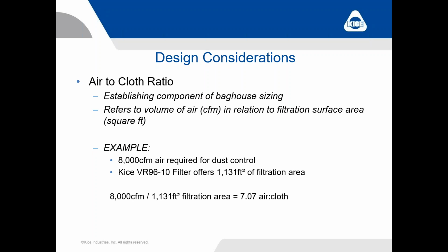If I take a filter bag out of this baghouse, cut a slit down one side and lay it flat on the ground, I can measure the flat surface of that bag. I can measure how many square feet of filtration area we have. That's how we find out how much filtration area is in the entire filter.